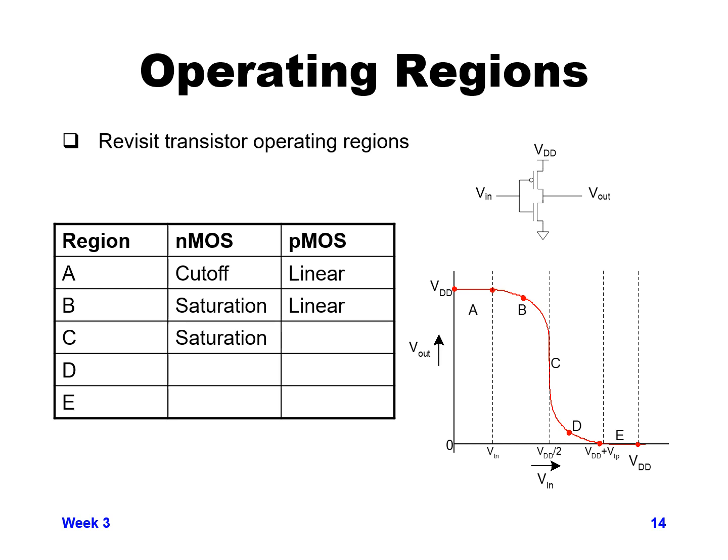When you get to the middle of the range, where you're in the region where you're switching quickly between VDD and ground, both your NMOS and PMOS devices are in the saturation regions. So you actually get a lot of current flow through both of them.